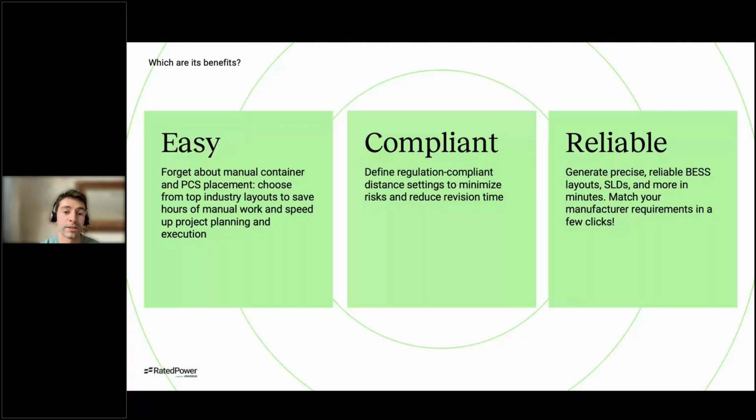You can generate the layout that you need for your project. It's compliant. As I mentioned, you can define the setbacks that you need, save them as a template, and then load them in each of the designs. So you reduce all this revision time and the risk of making an error in some input, and so on.